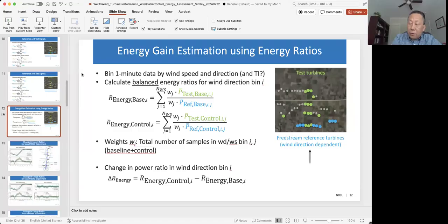Right. Okay, so one of the issues, Erica, I'm not sure you were in the meeting previously, especially in the early part of the year, that has been quite extensively discussed is the wind speed correction. In some of the studies here, you still use the turbine's own measurement, which is from the nacelle anemometer, I suppose, to measure the wind speed, which is already in the wake. And in my reading, I could be wrong, in your study, because you have multiple turbines, you use some of the reference turbines to provide a reference wind speed.